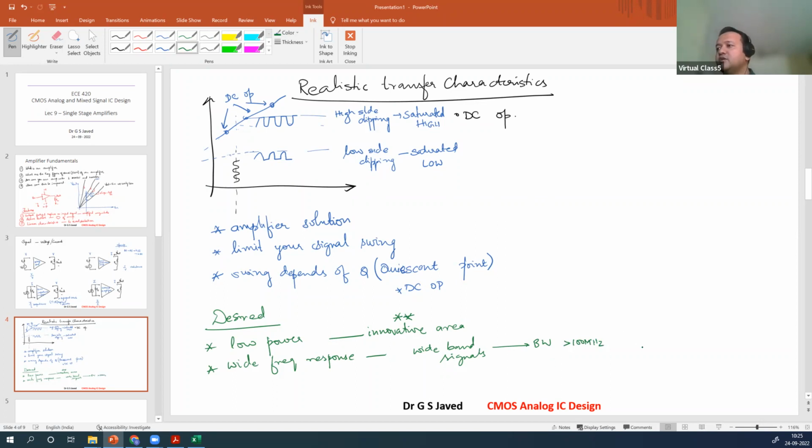So you will have designs centered across a particular frequency. This frequency say is 1 gigahertz. So your wideband would be 50 megahertz on each side. So the bandwidth will be starting from 950 megahertz to 1050 megahertz. This is one kind of a bandwidth.